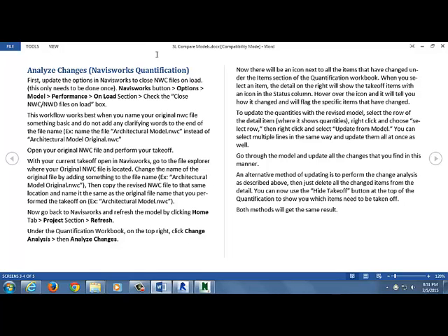If you hadn't closed it, and if you had that setting already checked, all you need to do after you change the name is just hit refresh. So it now looks for the same items because it thinks it's that same name, but really it's loading up version 2 because we changed the name. It's a little confusing. Oh, okay. So you had to change the name to the same as the NWF in order to open the 2.1. Exactly.